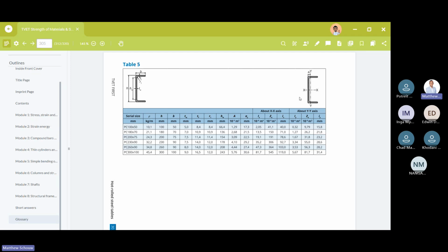That from the top down is actually the center. Obviously, this channel is not on the flange, it's attached by the web, I believe. So it's going to be the 259.6 plus the thickness, which is 9. Then we must subtract 30.6 or whatever value you have there. Are you guys with me? So that Y for the channel tells you exactly where the center of gravity is. Is that clear to you? That's that value. That's why they give it there.